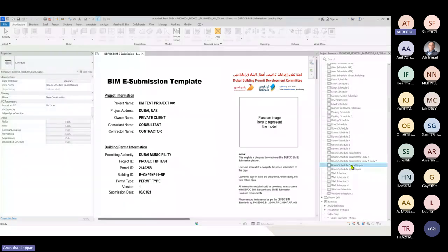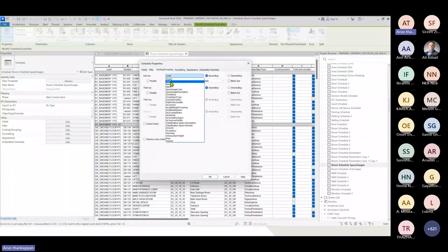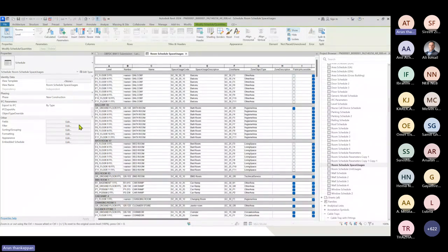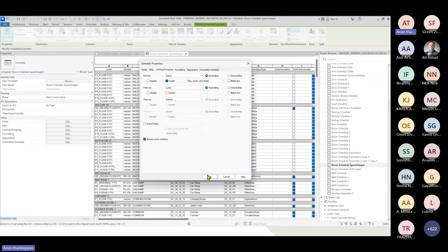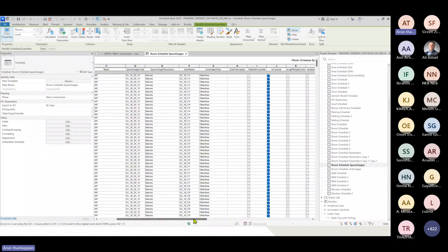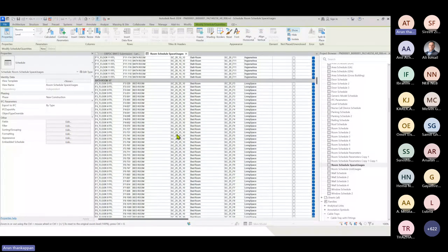You can always create a schedule for easy checking. You can check your parameters using the schedule, and you can play with it. You can arrange, and filter it using the name, and check whether you have added the correct parameters. So you can check each parameter using the schedule as the final checking, find errors from here and clear them.